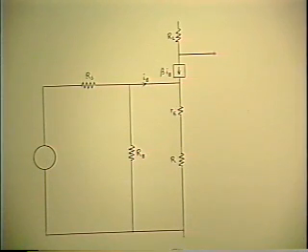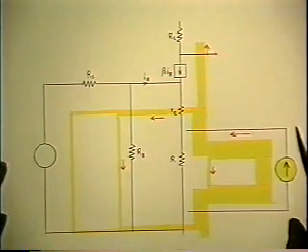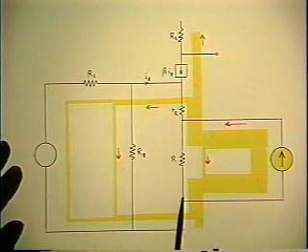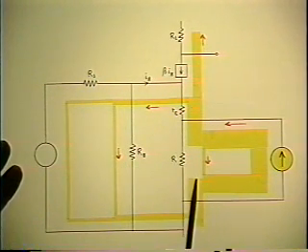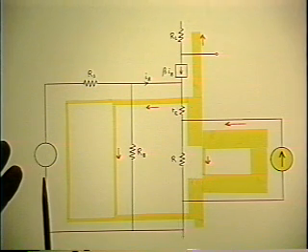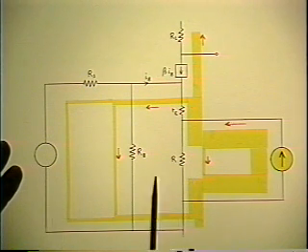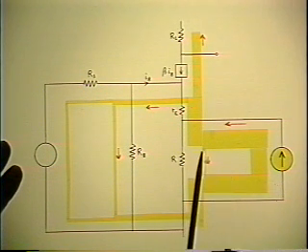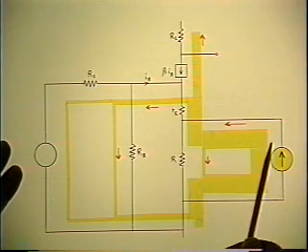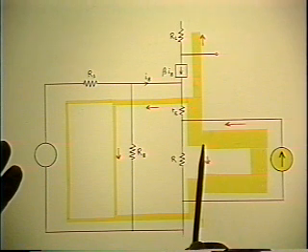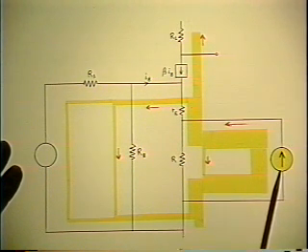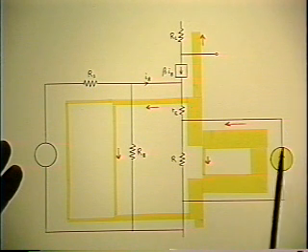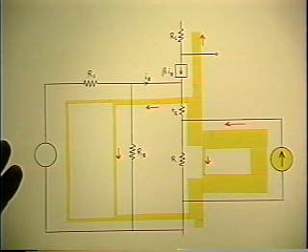So this is how we calculate ZD. We apply a second source across the terminals where the extra element is going to go, and we make the other source 0. So it's single injection at a different place. And this is what happens to the current. The current that you stuff in, now I've drawn an ideal current source. I keep changing it every time, just to emphasize it doesn't matter.